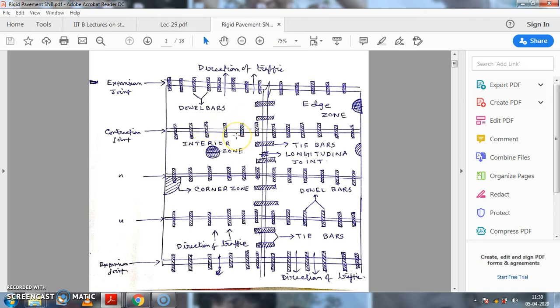Now, another important motto for expansion joint or contraction joint is that it distributes the load to the very next slab. So we can find another importance of dowel bar. Dowel bars provide load transfer from one slab to another slab, whereas expansion joint or contraction joint is also providing a juncture in between two slabs, and when the vehicular load is coming, one of the important motto of this expansion and contraction joint is that it is acting as the load transferer.